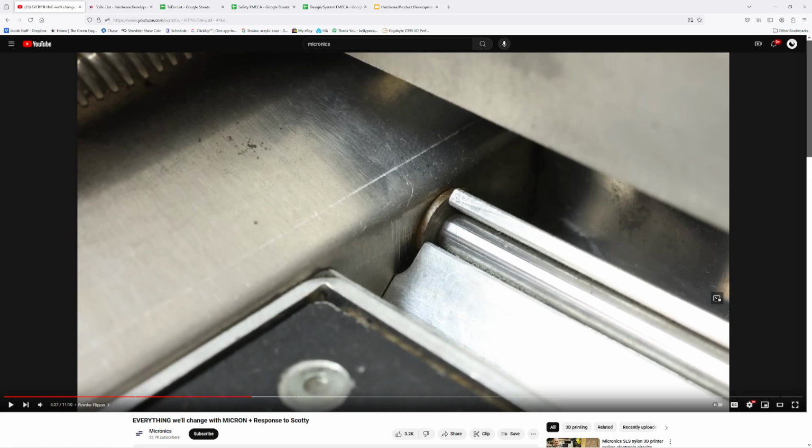So basically he's saying that this is a bushing here that allows this wear surface. So it's the oil impregnated bushing, right? And allows this shaft of the flipper to rotate on this, right? And then they're basically saying the powder, this very fine powder that gets basically everywhere, was getting inside here and jamming this guy up and causing failure. And you can see all these wear marks here of where it's rubbing with the powder against the wall, and then all the wear marks here on the front of the bushing.